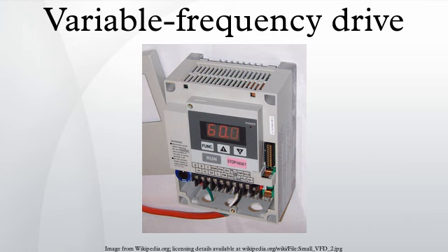The most basic rectifier converter for the VSI drive is configured as a 3-phase, 6-pulse, full-wave diode bridge. In a VSI drive, the DC link consists of a capacitor which smooths out the converter's DC output ripple and provides a stiff input to the inverter. This filtered DC voltage is converted to quasi-sinusoidal AC voltage output using the inverter's active switching elements. VSI drives provide higher power factor and lower harmonic distortion than phase-controlled current source inverter and load-commutated inverter drives. The drive controller can also be configured as a phase converter having single-phase converter input and 3-phase inverter output.